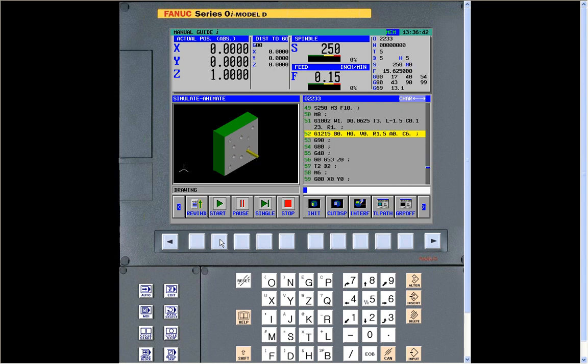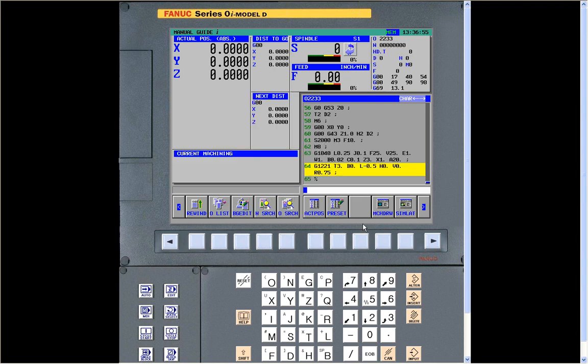Now tap all the 6 holes in the middle. Now we got an end mill going through and putting a round pocket in the middle. Okay? So now at this point, we've got that done. We also want to go through and add milling around the outside of it. We can use the same tool because it's big enough, it's strong enough to do that.